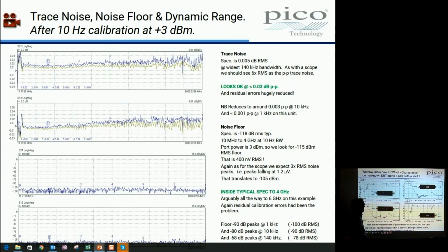We've got accurate measurements of its insertion loss, which is very deep indeed and couldn't possibly be seen by our oscilloscope. We know that it's got a little characteristic out here. If you inject something like, what's that, 4 gigahertz or so, it's got a response that pops back. Oh, it's just above 5 gigahertz. Sorry, I put these markers at 5. That's 5, so that's what, 5.3 gigahertz, something like that. So we can see a lot more of our DUT now. And these are just the S parameters plotted as log magnitude.